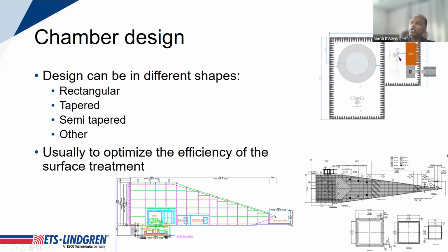For the component test, you have a similar setup, the transmit or receive antenna directly aligned with the device under test. So you measure direct coupling, or you transmit using this direct coupling within the beam width of the antenna. For different types of measurements, for antenna pattern measurements, for instance, something like a tapered chamber is very useful for a very broad frequency range when you're doing antenna pattern measurements. And this type of environment has a very different absorber type and absorber treatment, and a different operating frequency range, but again, it is optimized for this type of test.